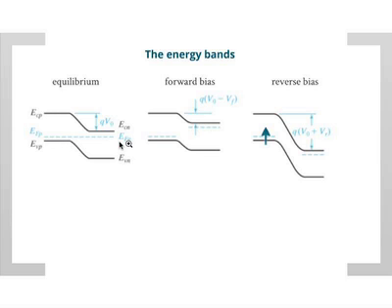Okay. Under forward bias, remember now we have a potential difference. So the Fermi levels actually don't need to be constant. It's not equilibrium anymore. Okay, and this is an important concept which we didn't really cover earlier, but you can have splitting of the Fermi levels. Okay, so when you apply a forward bias potential, the bending of these bands is decreased, as you can see.